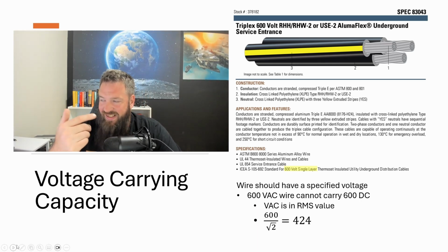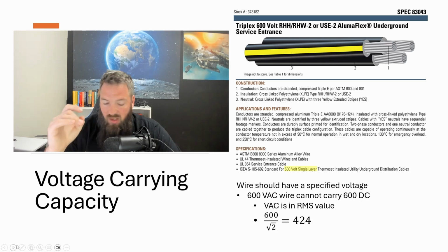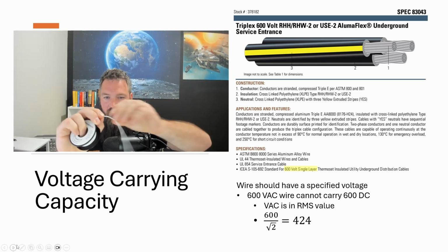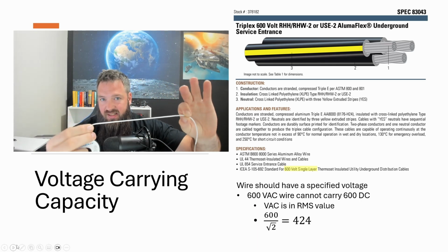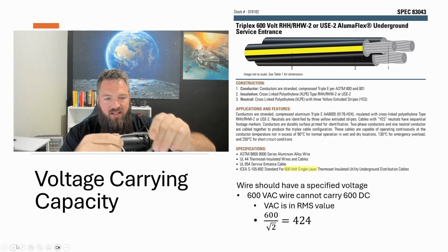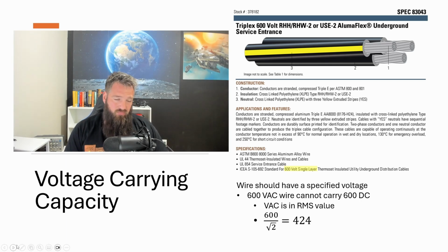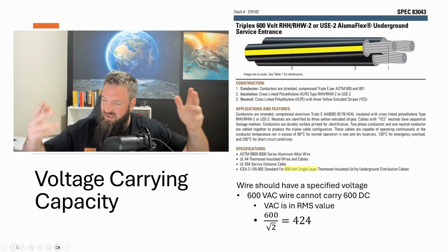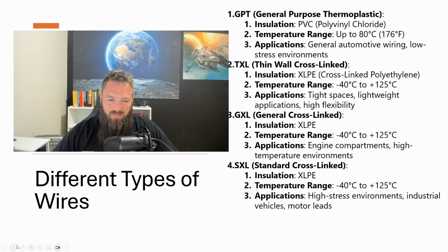So when they're testing these, they're going to apply a voltage on the outside of the wire right here. So they'll apply a voltage of this 600 volts. They'll apply 600 volts here, and then they turn around and they measure the leakage current on the actual wire. That's how they test for this. They've got more specific methods, but that's the basics.